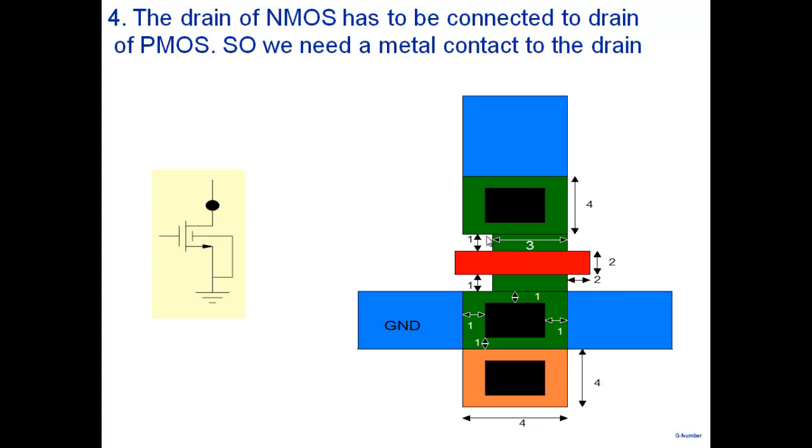Metals. So note, I made a contact here. This region that you saw here, I extended it here. And there's a metal here. So note that the metal always covers this contact. This blue metal is covering this here. Then only you can make the contact between the metal and the N plus. So the metal is there, underneath N plus is there, and in this region, that hole is there, which is filled with, again, metal, so making a contact. So now I've made this contact here, with this metal here. So now my NMOS transistor with a body contact is available here. But I've not made a contact to the poly also, I'll make it later on.